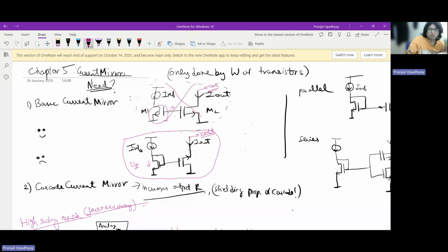This transistor will mirror current effectively from IREF to IOUT only when M2 is in saturation, which means that there is a certain constraint on the swing limit of this VOUT node. This brings the problem of swing limitations, although this is a very simple, very basic current mirror.